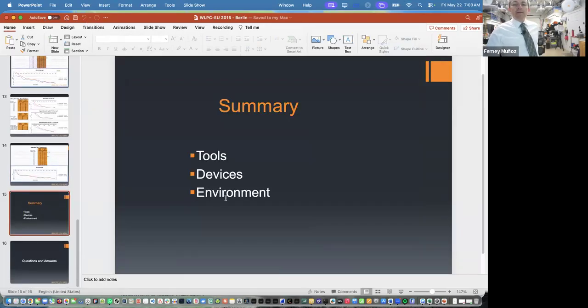Keep in mind that the environment is what you're measuring. So what else is around you? What structure do you have? Do you have metal walls, metal doors, metal ceilings, metal surroundings? Because then you might have a lot of reflections and you're going to get multiple readings. You have to measure multiple times, not just once. Oh, 3 dB. Like, no, go measure again.